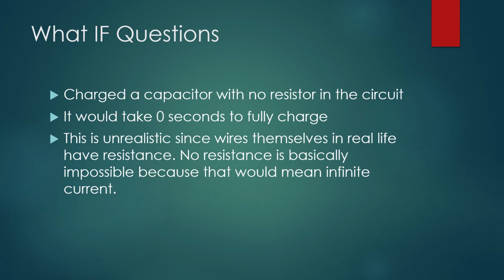What-if question: if a charged capacitor with no resistor were in the circuit, it would take 0 seconds to fully charge. Now, this is unrealistic because wires do carry resistance. In our models, we assume that they are ideal wires and have no resistance. But all wires in real life carry resistance, and no capacitor can be instantly charged or discharged. That would mean infinite current, and that is not a real thing.